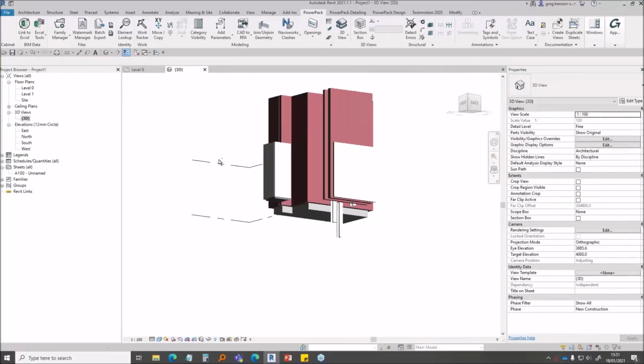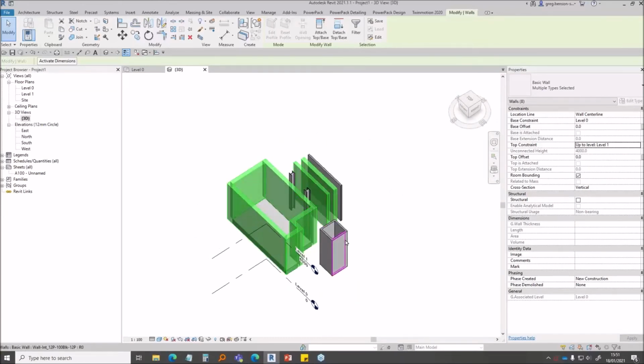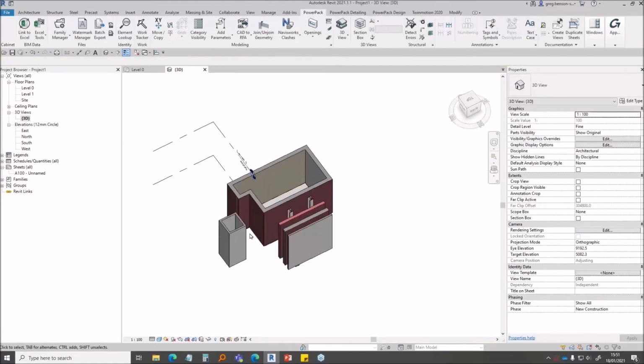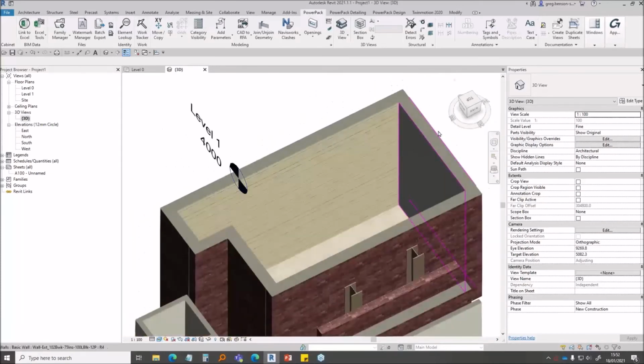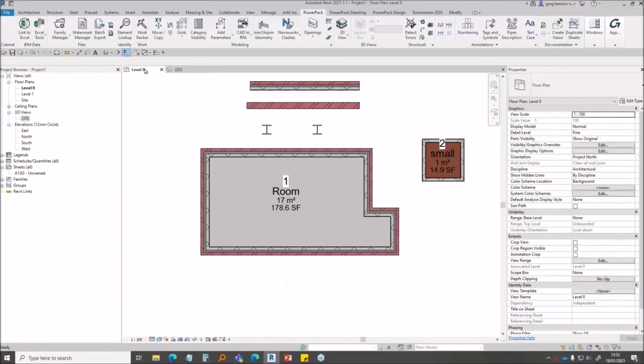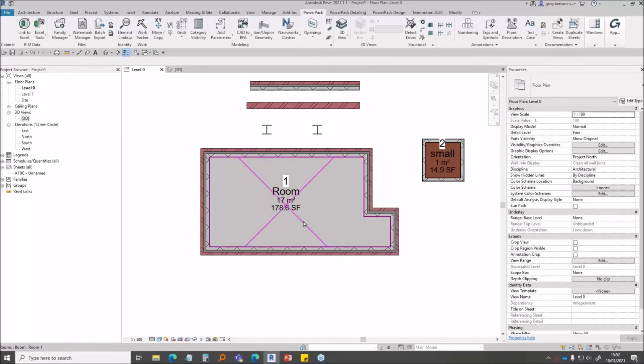And in our 3D view, just to check, let's just select these walls and connect them to the level 1. That's better. All right, let's have a look. So that long wall now, okay, if I change this into realistic, we've got our timber cladding on this side, and the rest of this has got plaster. Let's see how the properties react to that. Need to do a quick update because we have changed the properties of the building. Okay, so add parameter, room and finishes. Select that room and click on the finish button. Off we go. Boom. Right, let's click on the room, see what it says.